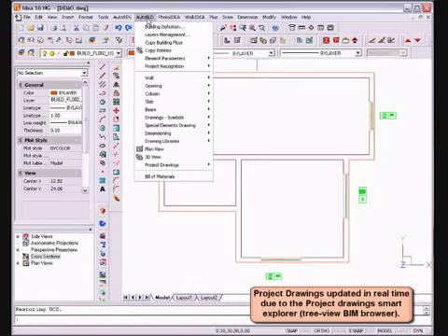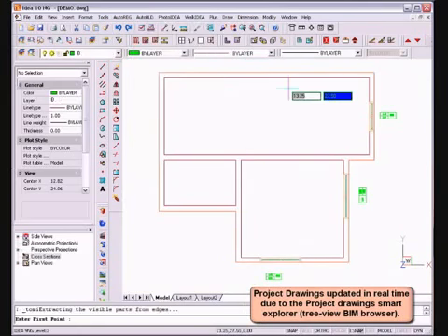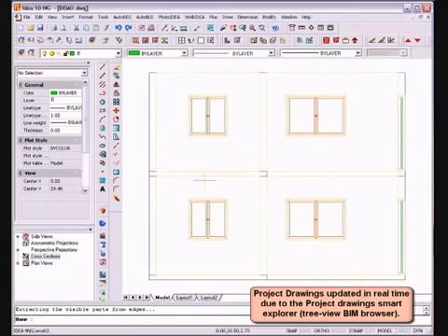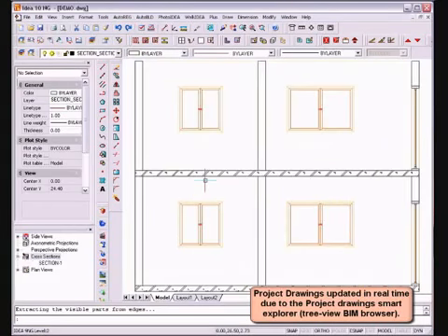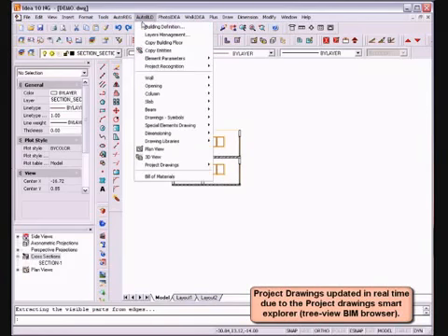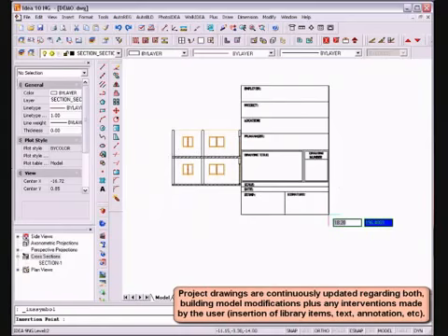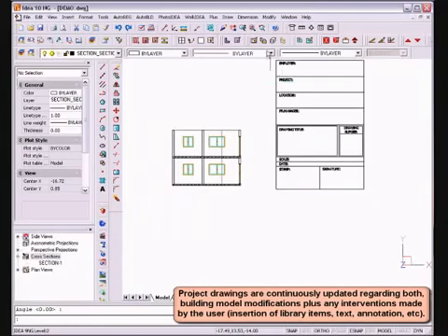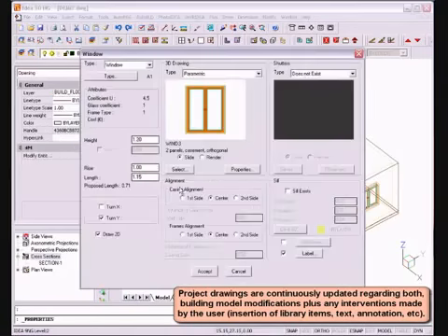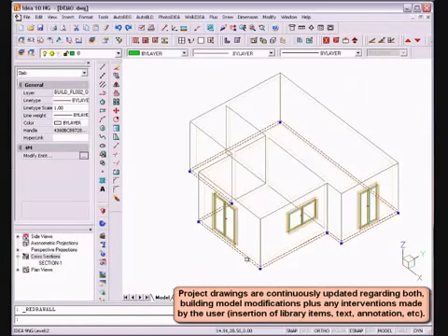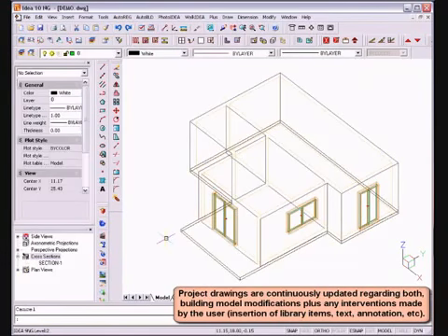You will probably need also some 2D views of your project. Let's create, for example, a section view. This will create a new DWG file you will see in your project tree. You can modify these 2D drawings to insert, for example, a title block. And if you modify the 3D project, the 2D drawings will be automatically updated. Here we modify the slab, and we can see it already in the section view.